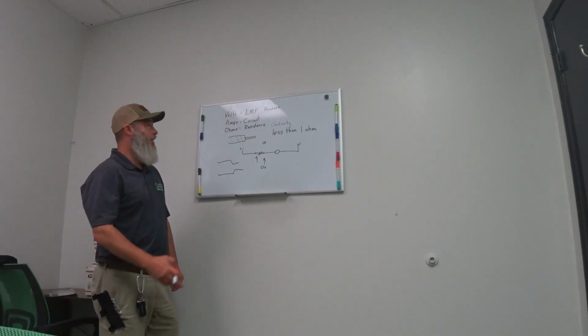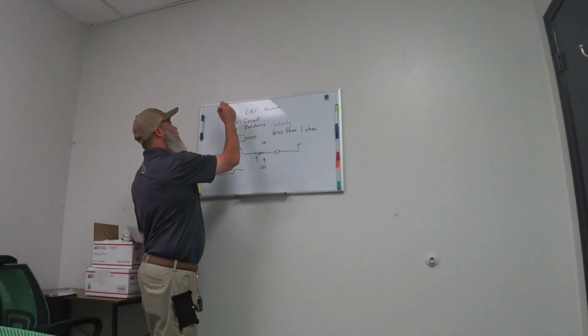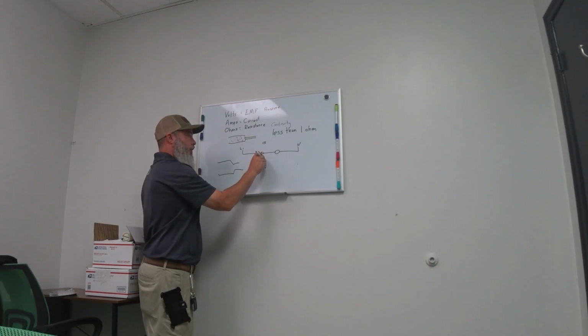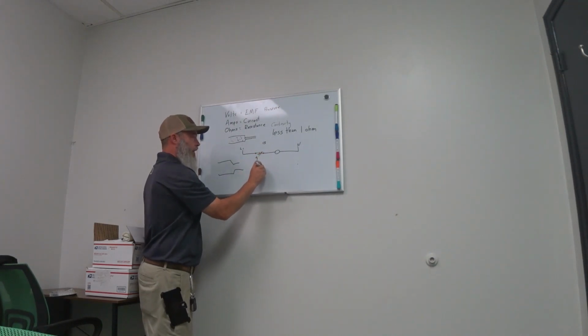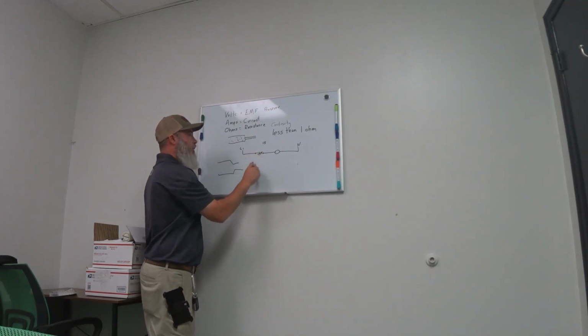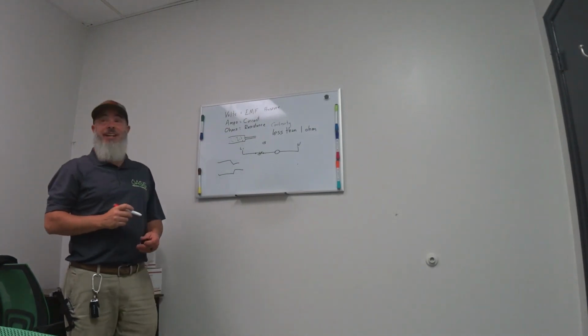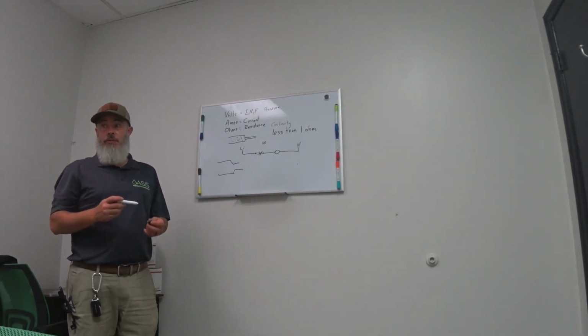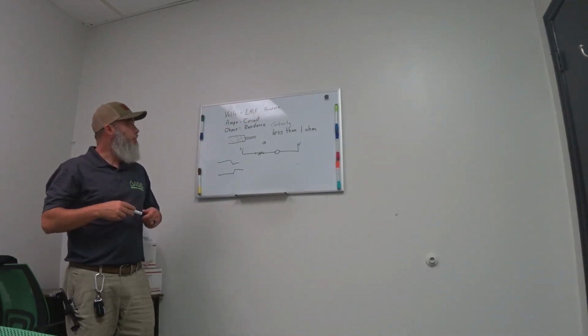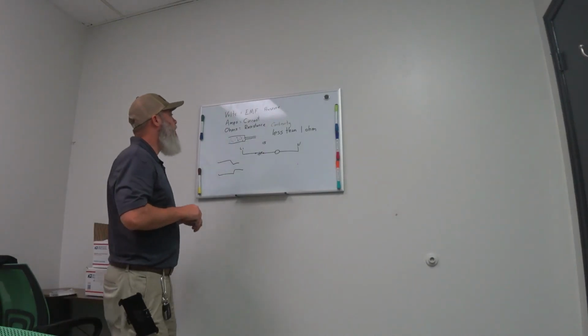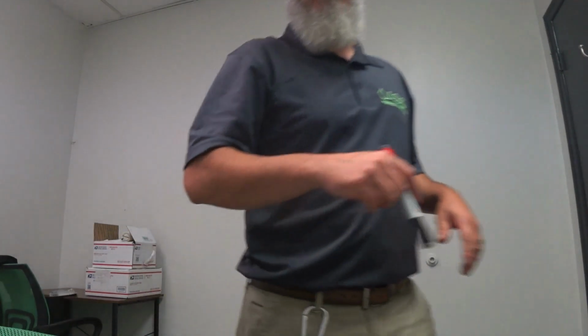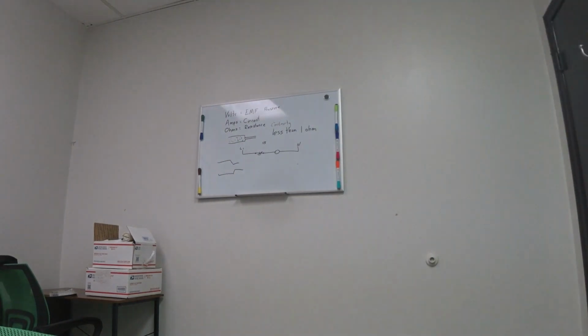So we also use volts to troubleshoot in a lot of occasions. Where do we have power? Where do we not have power? Where should we have power? See where it stops flowing and trace it back. Check your switches.